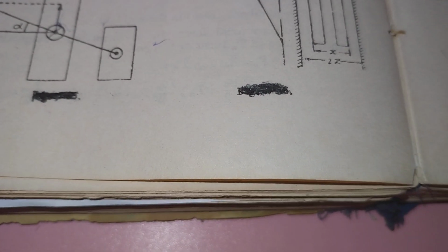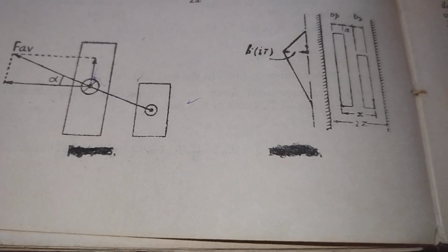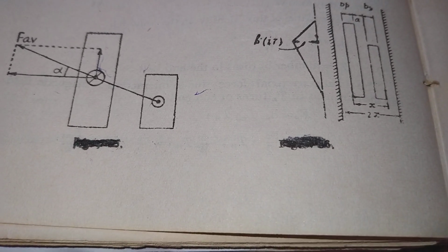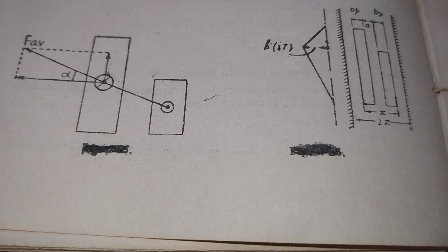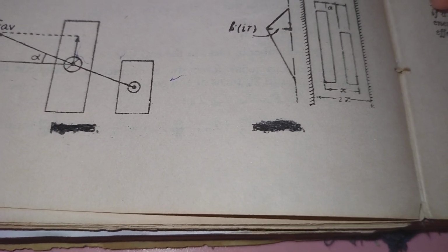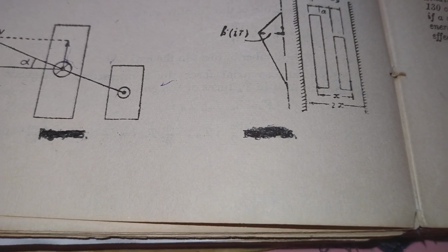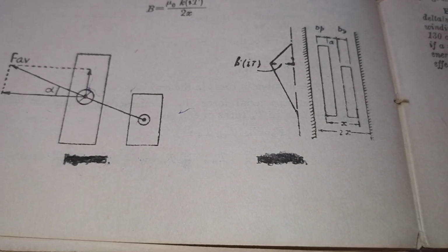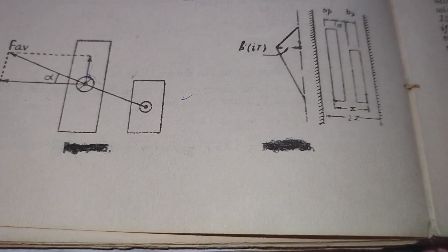Ideal symmetry, which means windings of the same lengths symmetrically placed with respect to each other, can never be obtained in practice because the transformers are provided with taps which include as well as exclude a part of the winding during service. This asymmetry results in axial displacement of windings.